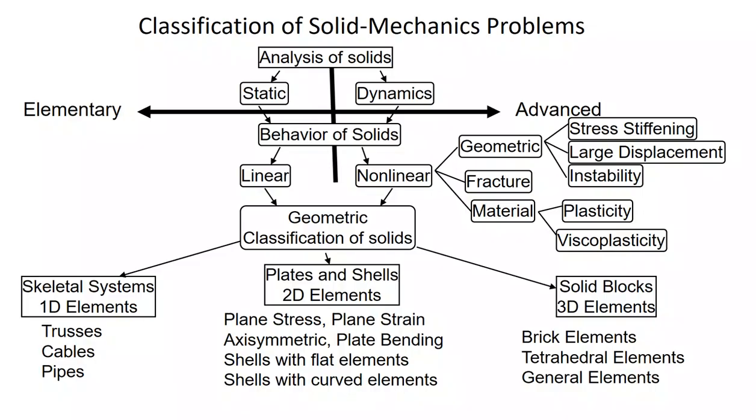In such cases, we can eliminate the thickness as a major parameter. We only consider breadth and height as the major parameters. The secondary parameter we give is the thickness. Finally, we solve the problem in a 2D manner and get the results for the 3D output. Such cases we can consider as 2D elements.